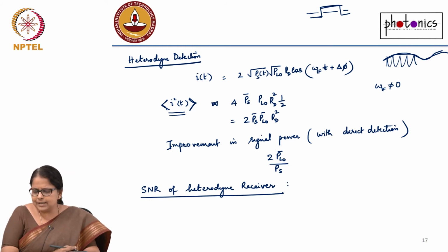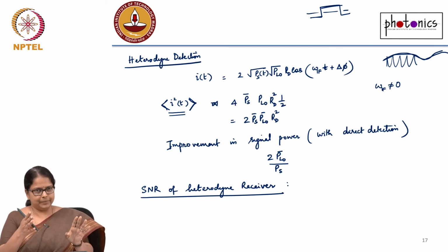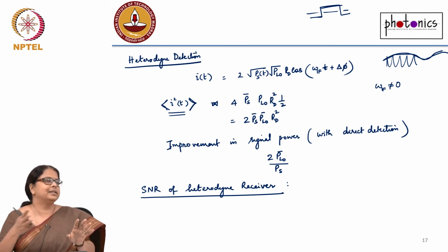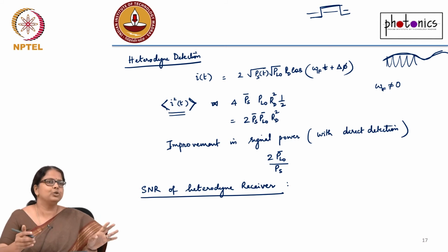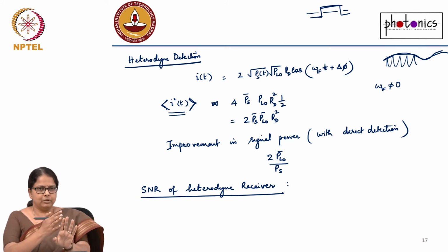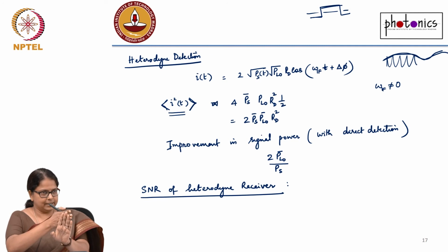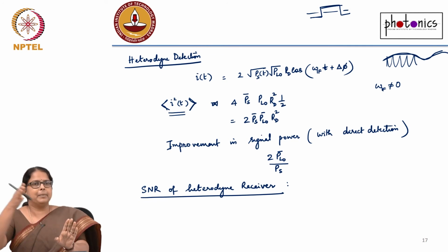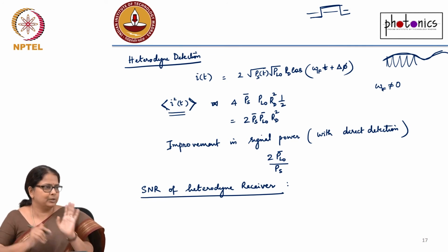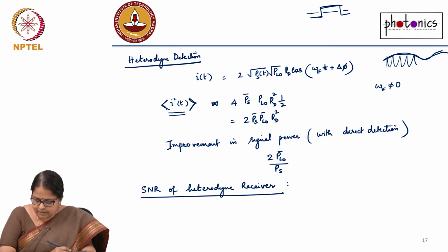Now there are small things like, what would your IF be? Should it be outside the bandwidth of the signal, inside the bandwidth of the signal, and certain things you may want to consider, because you may not want to interfere with your signal bandwidth. So you'll try to keep your omega IF outside the signal bandwidth and so on. Right? But this is a real test. What is your intuition?